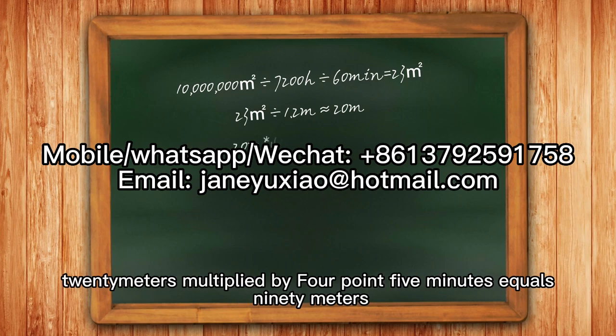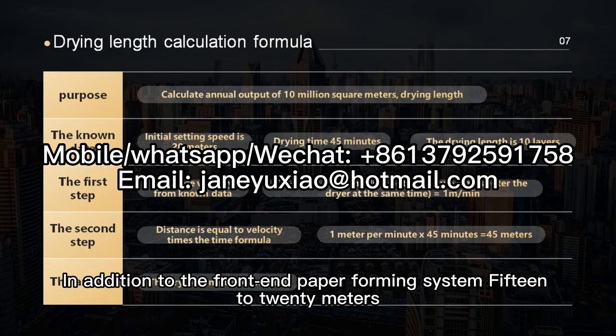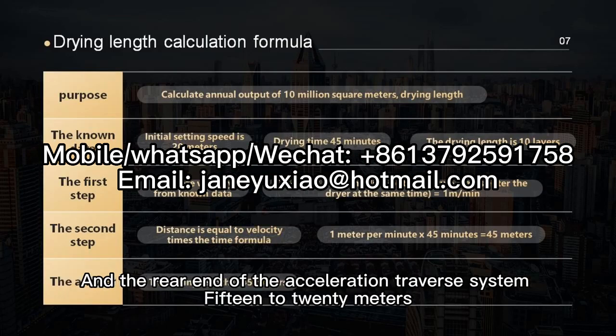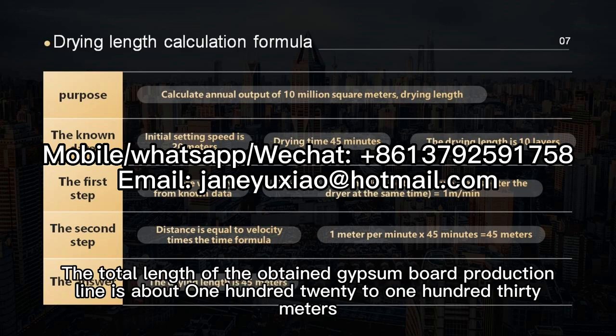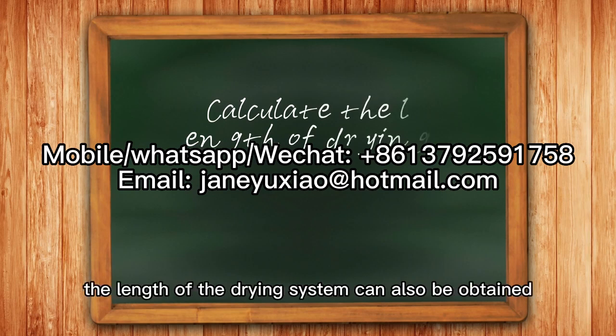20 meters multiplied by 4.5 minutes equals 90 meters, which is the length of the initial setting system. In addition, the front paper forming system is 15 to 20 meters, and the rear-end acceleration traverse system is 15 to 20 meters. The total length of the gypsum board production line is about 120 to 130 meters. Through the above calculation, the length of the drying system can also be obtained.